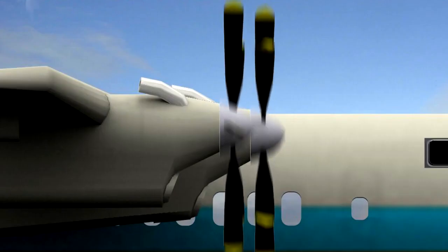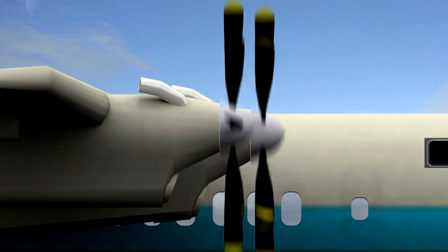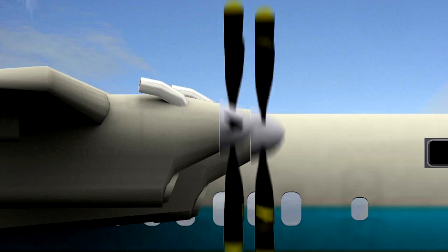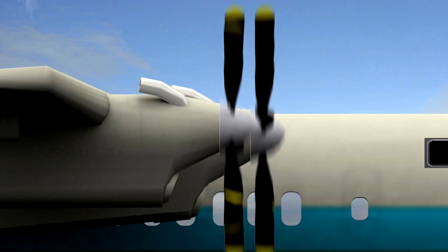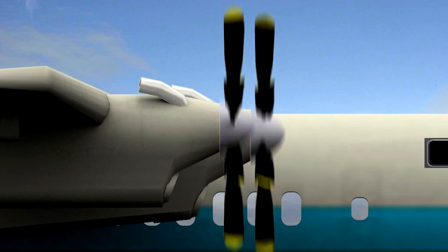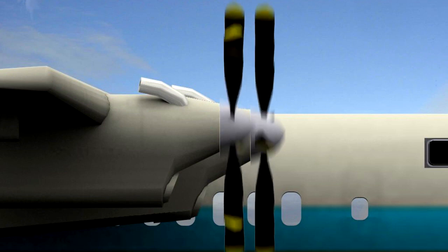Large turbopropeller aeroplanes are also able to generate reverse thrust by redirecting the airflow forwards, but they do so in a very different way than that employed by a jet engine. For forward flight, the propeller blade is angled in such a way as to displace air backwards, thus producing forward thrust. This produces a forward force, as shown.